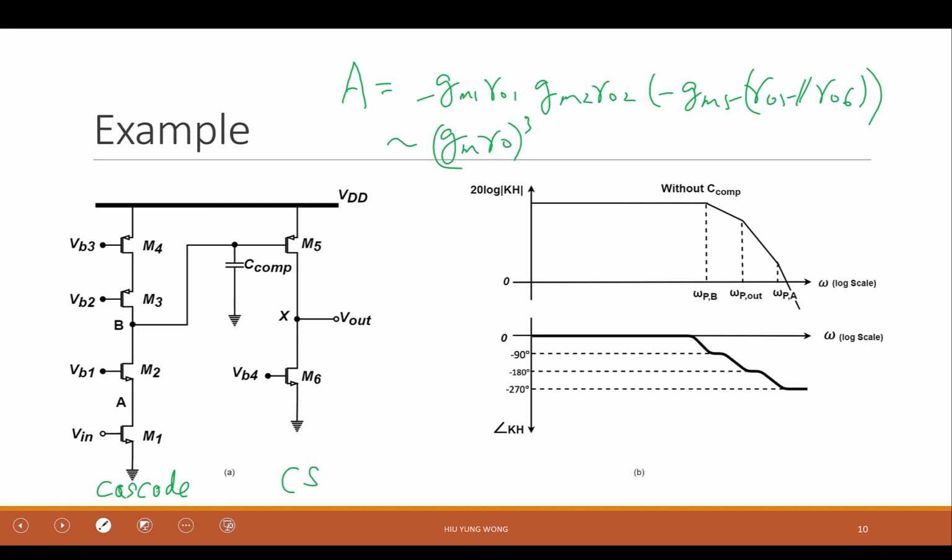But this circuit is not going to work if you just use it in feedback, because it's going to oscillate. It easily has 3 poles, right? If you really solve the circuit, you find that one is the input pole, right? This input pole, does it have Miller cap? Do you remember if there's Miller cap? I mean, both answers will be correct, but you need to explain why.